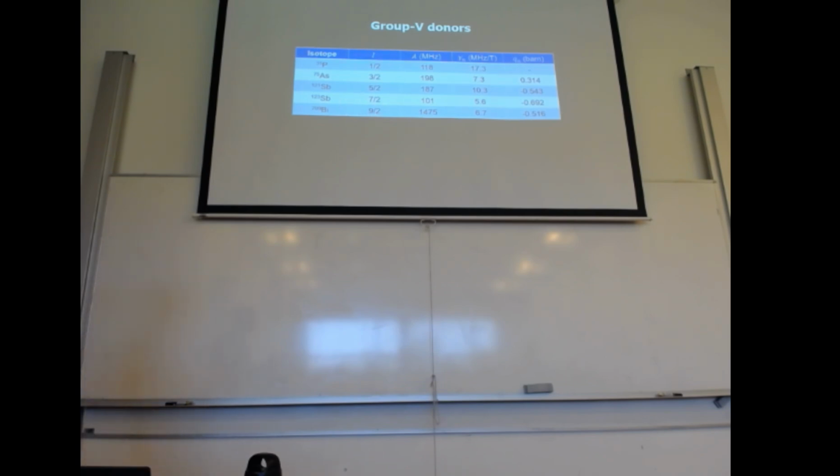Bismuth is quite interesting because it also has a very large hyperfine, so there is zero field splitting there. Anyway, for our purposes, to operate it exactly the same way as we use the 31 phosphorus, it is most convenient not to have such a very large hyperfine, so we stick to 123 antimony. Another good thing is that the implantation of antimony is well understood and controlled. So, yeah, a fairly arbitrary choice of ours to focus on 123 antimony, but we optimized it to maximize the spin quantum number for the nucleus that we could get given some of these constraints.